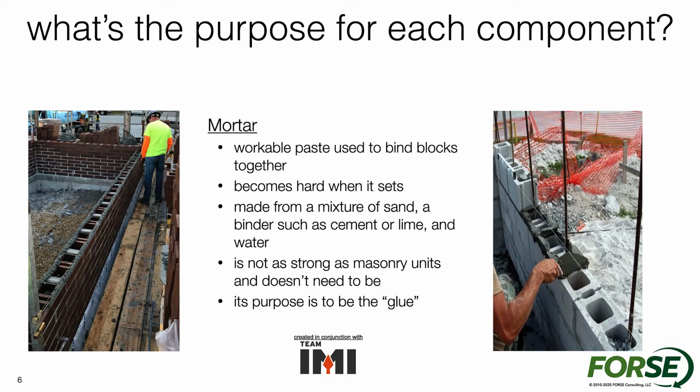So really a primary purpose of the mortar is going to be the constructability component of placing the mortar. The strength of the mortar tends not to be as important simply because the mortar ends up being in a very small confined bed within the masonry wall.